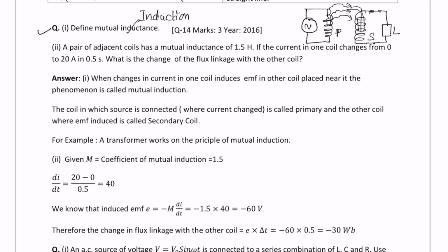To communicate the magnetic flux from primary to secondary, if the voltage is very high, we can keep air. This is called an air core transformer. If we don't want magnetic flux leakage, we can keep a laminated iron path, since permeability, the degree of allowance to magnetic lines of force, is more in iron.